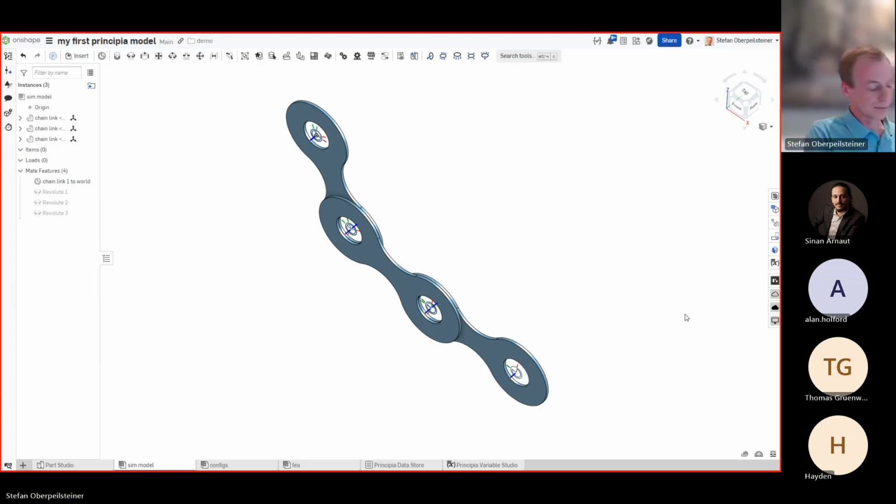It means if Onshape finds that your model is over-specified, that means you have some double fixed joints. That means you have connected your system to your surrounding 2 times, and it's something like over constraining. Onshape has an automatic detection of this.